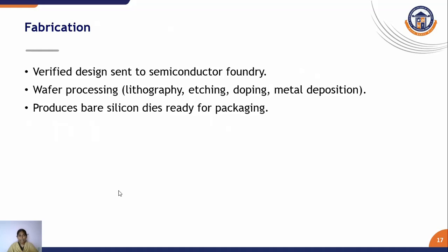Here we perform the wafer processing. In wafer processing, as we already know, there are lithography, etching, doping, and metal deposition. Here we produce bare silicon dies ready for packaging. Our design die is ready here.